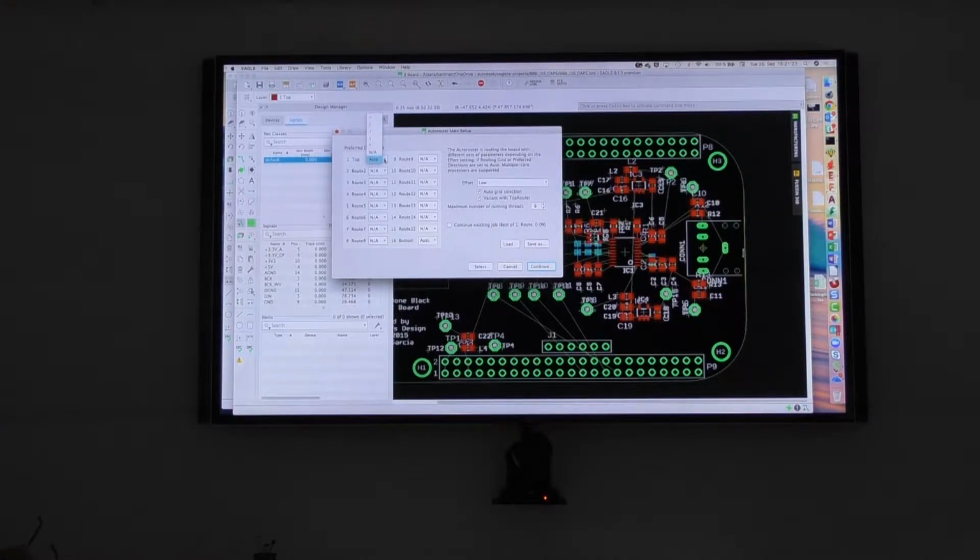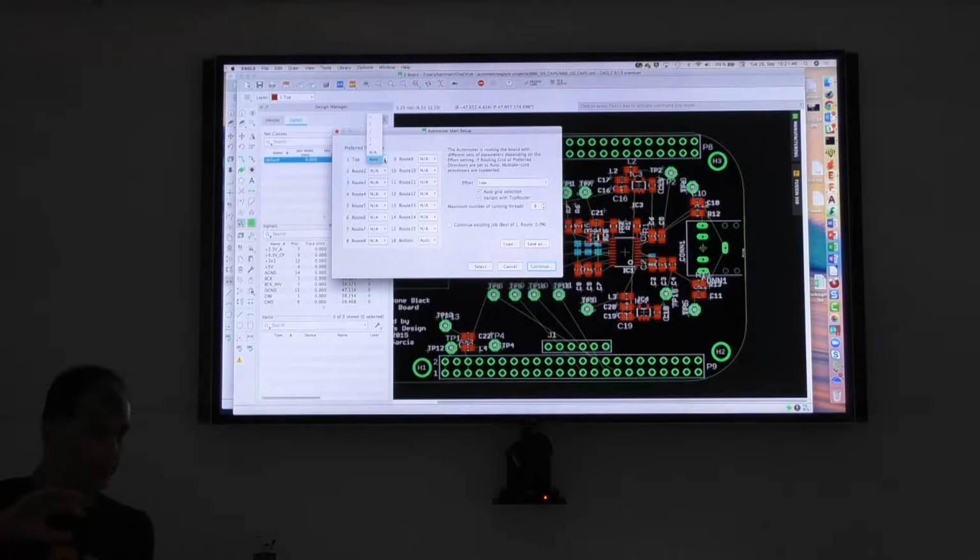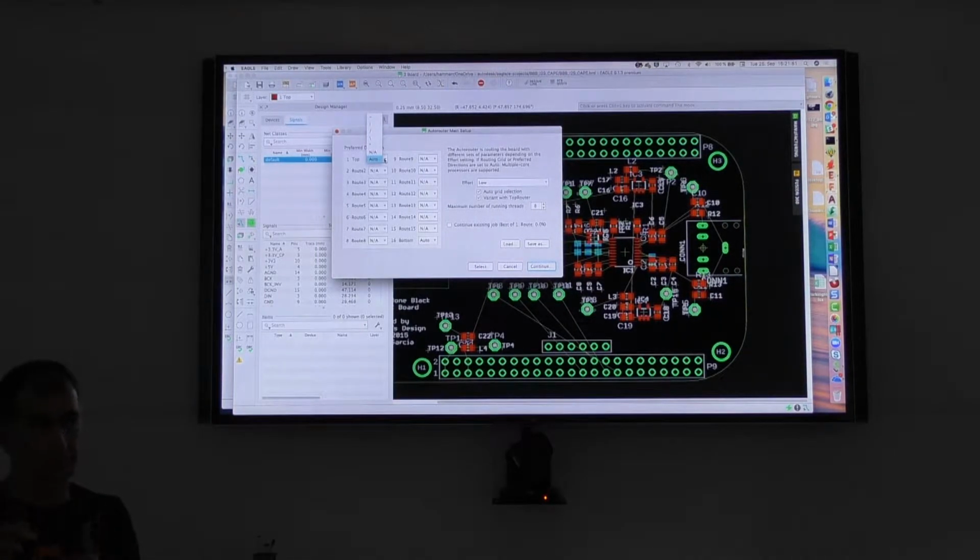You see these characters: preferred direction horizontal, vertical, 45 degrees, 135 degrees, and the asterisk stands for no preferred direction. What does this mean? If I have a two-layer board, then Eagle tries, if possible, to have the main direction on the top layer, for example, horizontal, and on the bottom vertical. That makes it easier to get connections. I use vias to go from here to there.